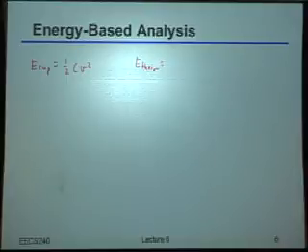Yeah, it's just kT, right? Okay, well, what do you think I'm going to do next? Yeah, I'm just going to say, well, the energy that's available from the noise should be equal to whatever energy I'm storing on the capacitor, because there's nothing else I can do, right? Okay, well, so if I do that, hopefully it should be very obvious that I'm going to get that 1/2 CV squared is equal to kT.